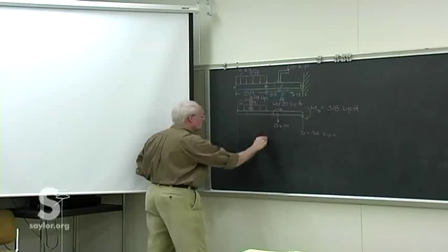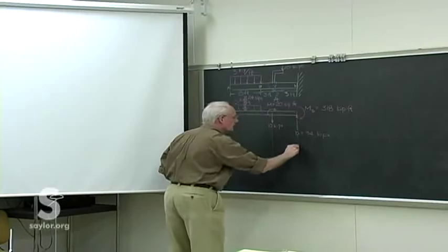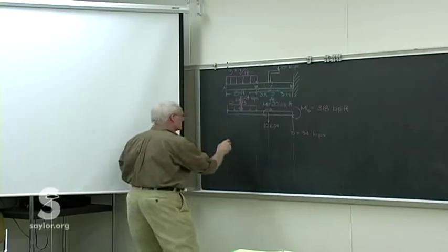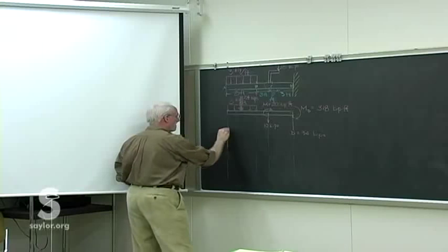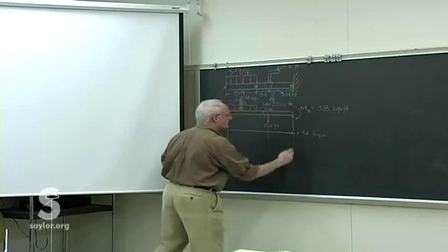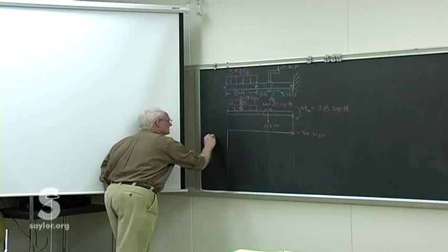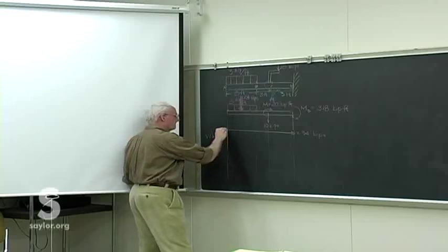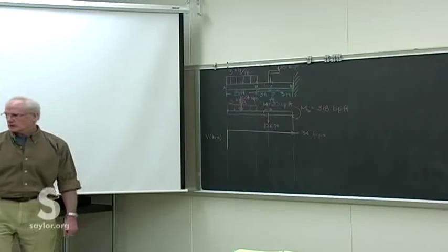And then we can draw our shear moment diagrams. And we can speed it up a little bit if we remember some of our graphical relations between these. I happen to know offhand that we only have negative shear on this one, so I can go ahead and draw the axes like that, just to make it a little bit easier for us.